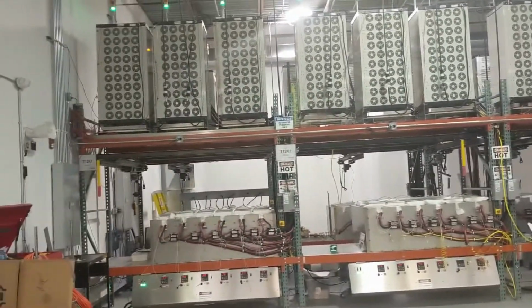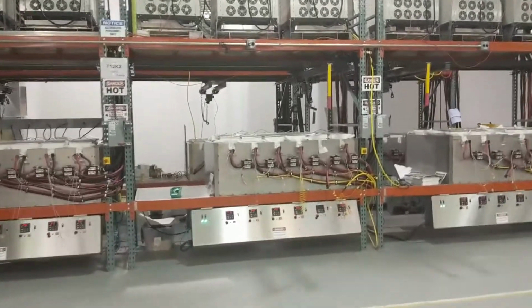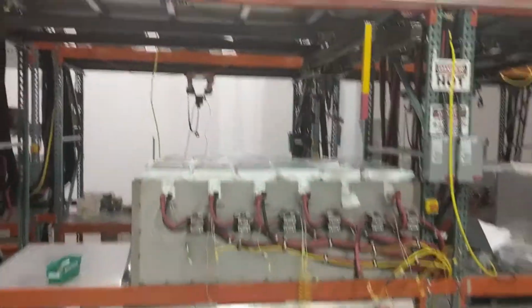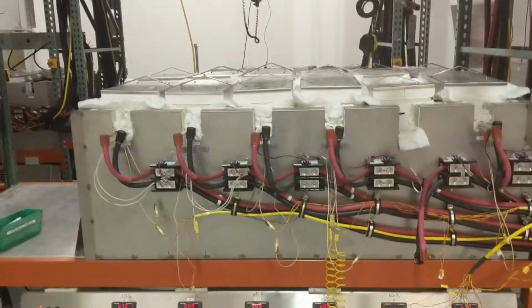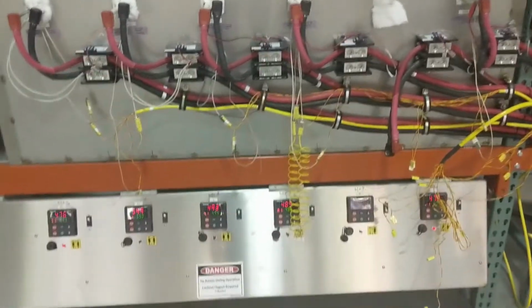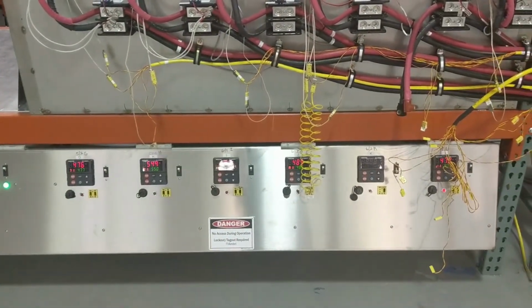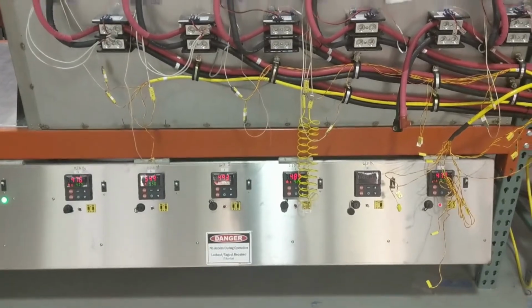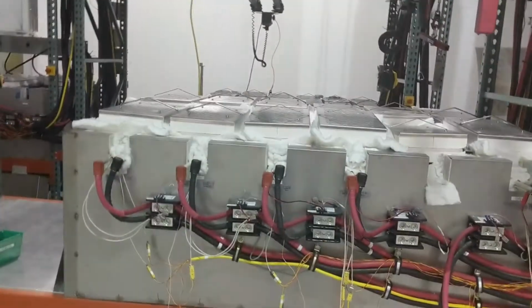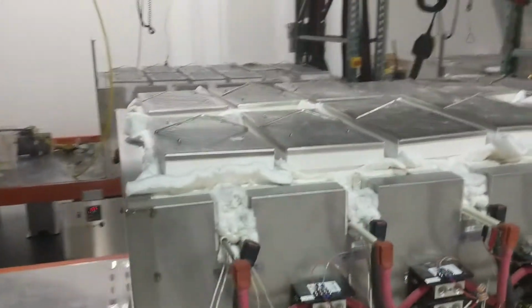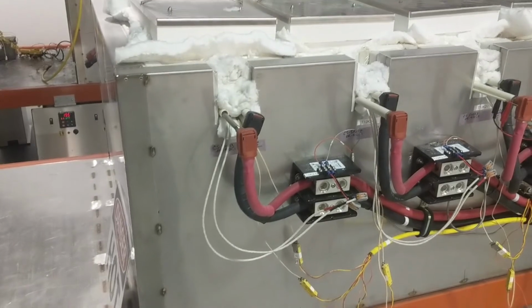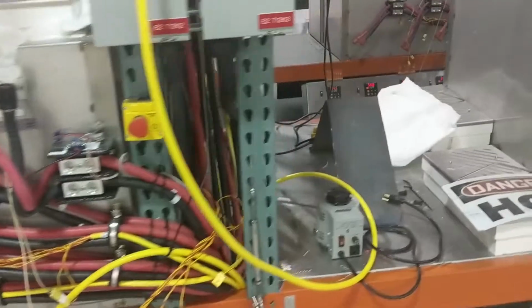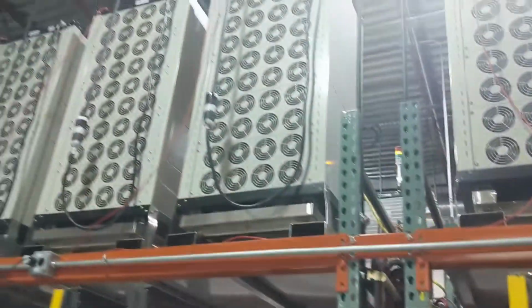So these are our commercial cell testing stands. We'll zoom in on one of these units here. You can see the commercially provided battery tester systems are located on the top of these racks, and the furnaces are located underneath. So these furnaces are hot. They're operating at anywhere between 475 Celsius and 550 degrees Celsius. And each of these bays here contains one cell. There's an insulated cap on the top. There's current leads and voltage sense lines coming out of each bay. Those current leads and voltage sense lines pass up to those battery testing systems on the very top.